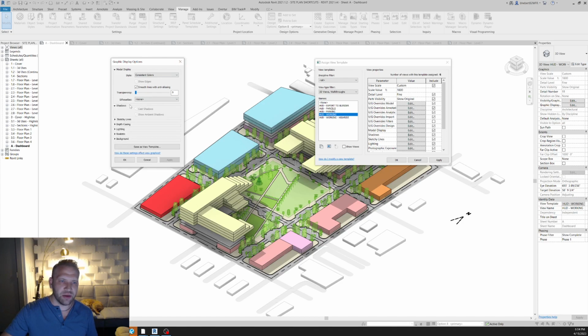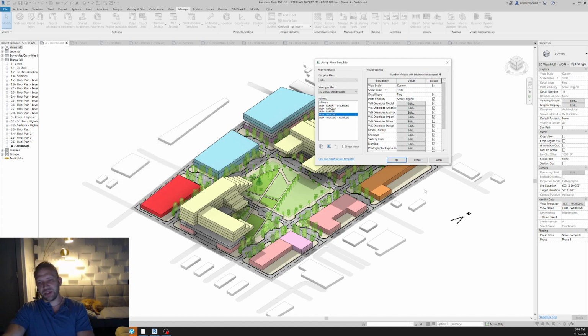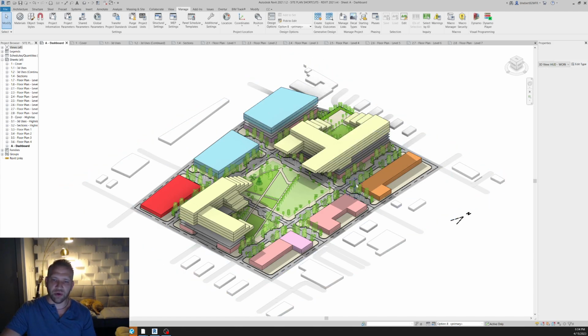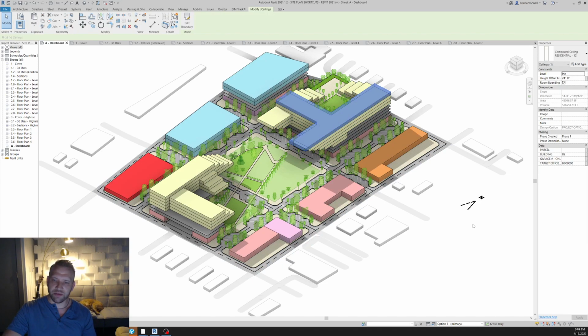So you can check out my shadow settings from here. I'm casting shadows and I'm showing ambient shadows. It kind of gives it that little bit of uneven shading, which gives it a little bit more of a realistic vibe. And on my lighting, I've got the sun at 30, ambient light 26, and shadows at 24. Those are the settings that I'm using essentially to achieve overall this effect. Not to mention, the colors. I've chosen the colors.